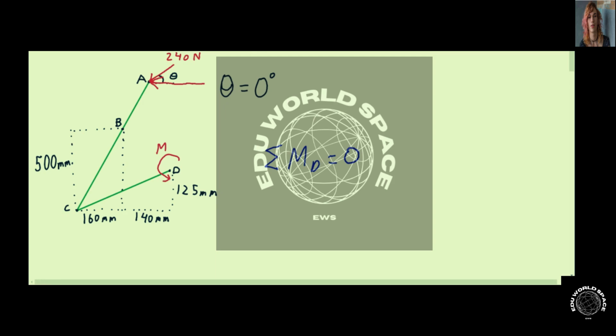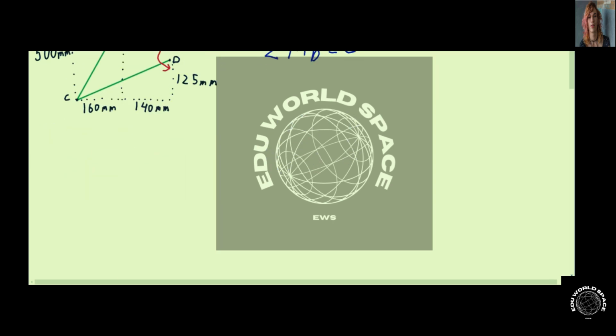So next we're going to solve for the x component of the force applied at C. And just by looking at the free body diagram, since there's only a horizontal force inputted, we know that there's also another horizontal force at C that's in the opposite direction. So we can say that the force, the x component at C is equal to 240 newtons.